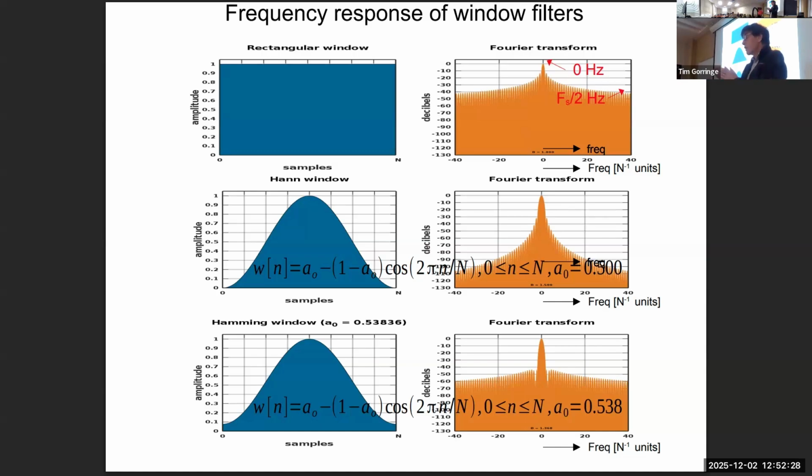When you carry out the average over the window, because that window corresponds to one period, the average is going to be 0. Or if the frequency is such, or the period is such, that there's 2 complete cycles in your window, when you average those 2 complete cycles in your window, then that signal will also not get through the filter.